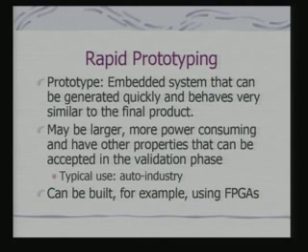So, from there we can build FPGAs, we can even execute our code on these FPGA based prototypes, and verify the overall design. Once that overall design is verified, now these FPGAs can be converted to an ASIC or SoC as the case may be.